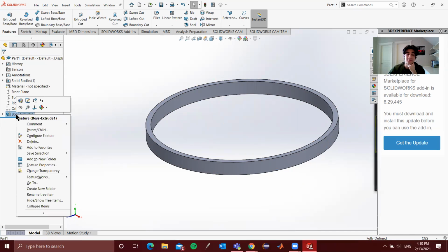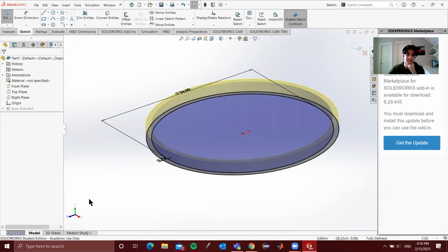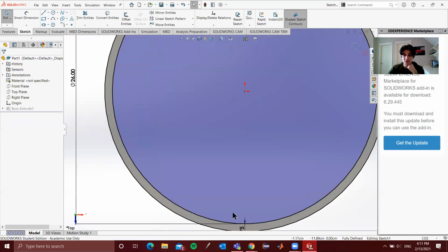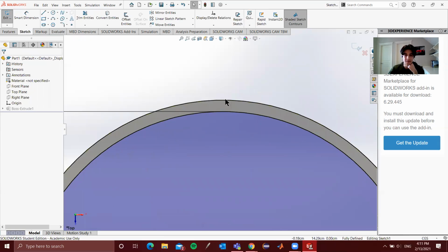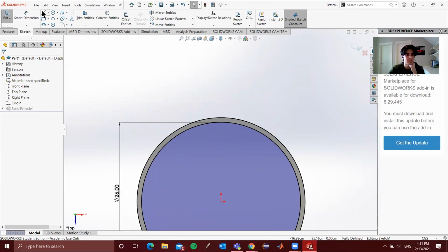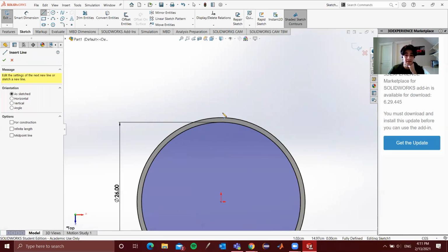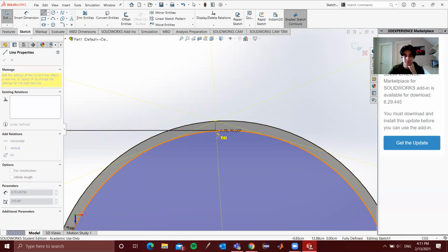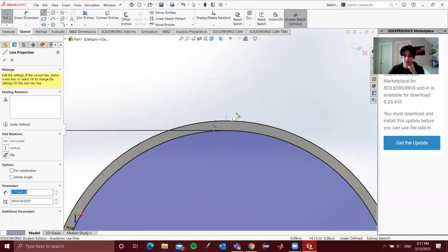So as a result of that, what I'm going to do is update this sketch. And it can't be fused into one circle to begin with, because if you do that, you can't actually adjust the sketch. So I'm going to create a small little opening here. Let's say up here. So I'm going to draw 2 vertical lines emanating from the first circle. And precision doesn't really matter at the moment. You can allow that to attach anywhere. And I'm going to draw another one too.